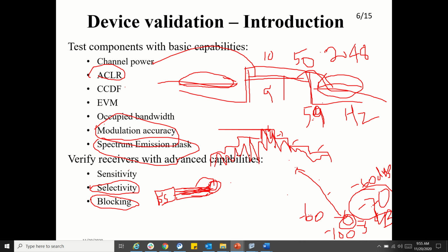So in the presence of an interference signal, how your UE throughput is affected, if you are measuring throughput, that we will analyze using the blocking technique. There is in-band blocking, out-of-band blocking, several things. In-band blocking means, for example, you have a set of bands allocated, for example C-V2X, which is 5855.2 to 5920 MHz.